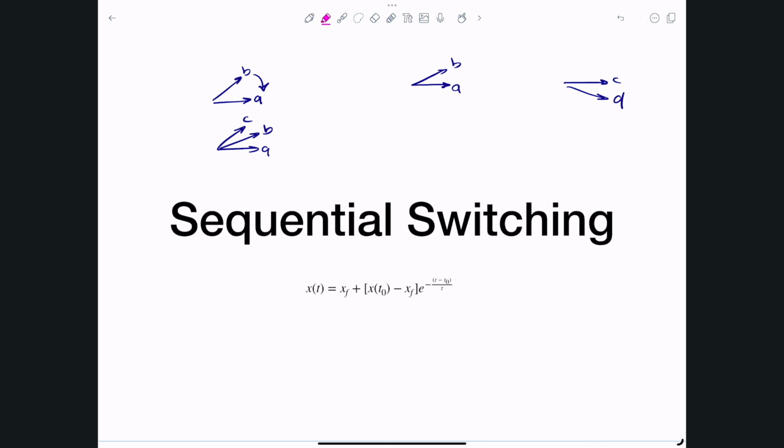However, we have to pay a little bit more attention to what t0 is, because t0 becomes 0 for the very first switching, and maybe after 40 milliseconds, this is what I did in here, t0 becomes 40 milliseconds. So the initial condition will definitely change between the different switching. The key thing to solve sequential switching circuits is to draw the circuit at different stages: right before the first switch, then right after that first switch, and then right before the second switch, and so forth.